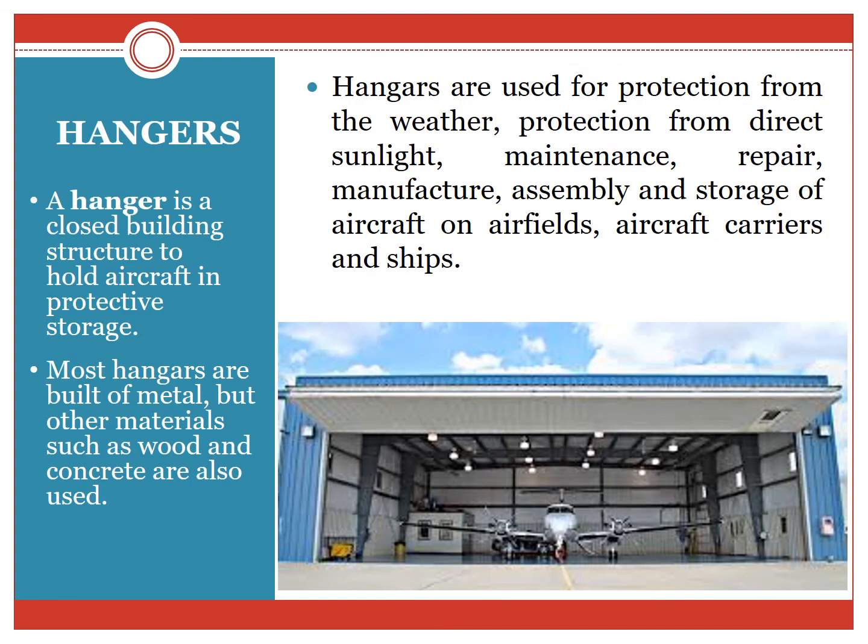Hangars. Now what is a hangar? The main function of a hangar is to provide an enclosure for servicing, housing, and repairing of the aircraft. As you can see in this figure, an aircraft is housed in the hangar. They are usually constructed of steel framework covered with galvanized iron sheet. The service hangars are provided with machine shops and stores for spare parts. The size of a hangar depends on the size of the aircraft and its turning radius.